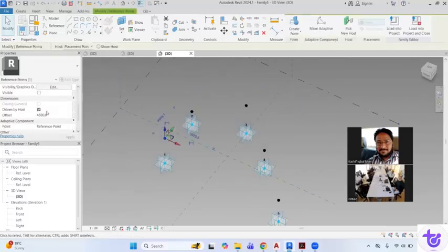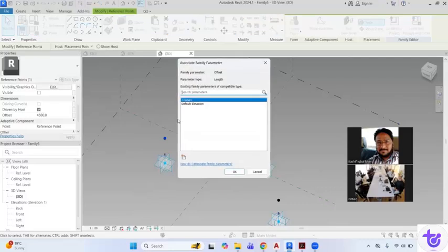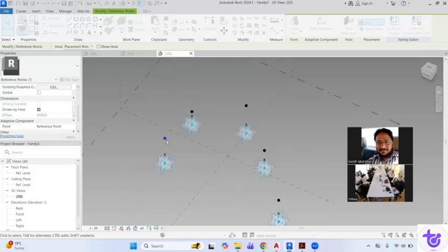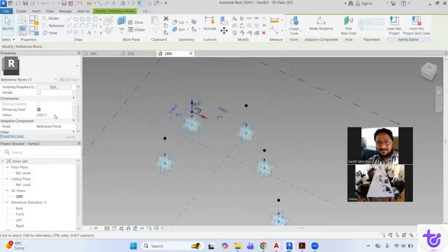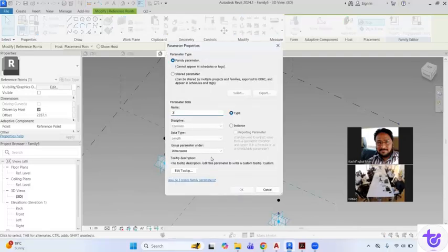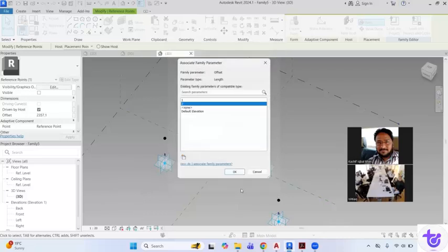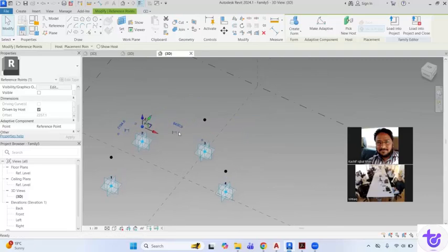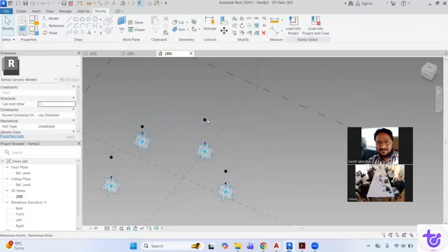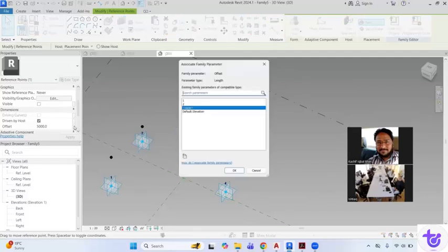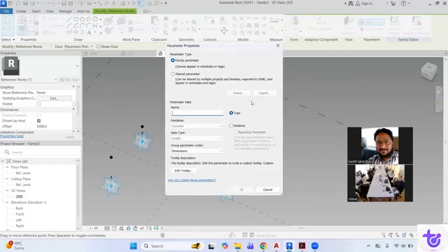Here I'm going to put a parameter. Take it as an instance. You can give any name. I'm going to give 1, 2, 3, 4, 5 normally, the same as the adaptive point names. This is adaptive point 2. On top of it, we have got a height parameter, which is 2. And then here again, we'll put a new parameter.